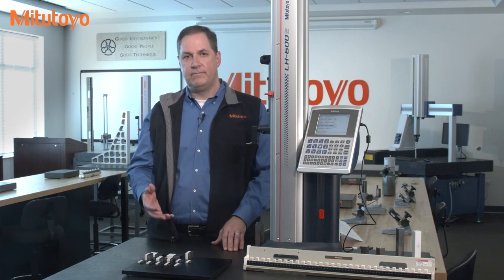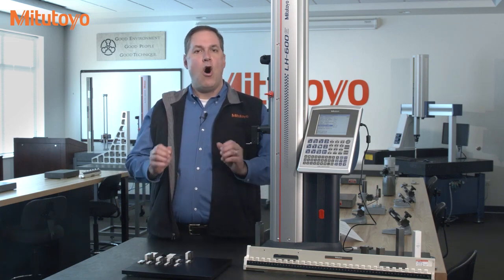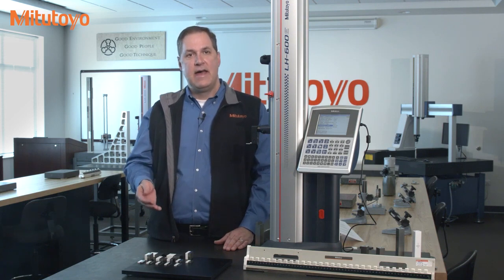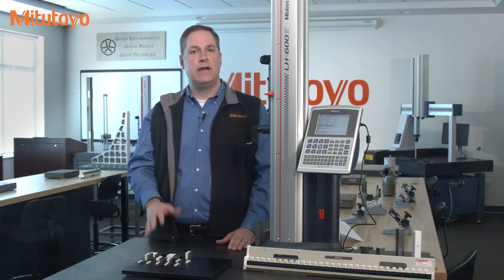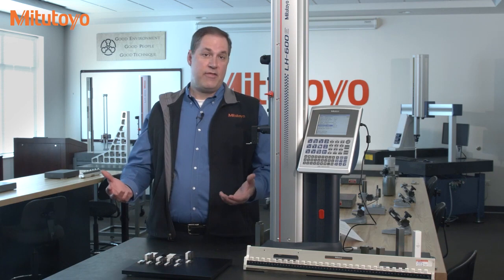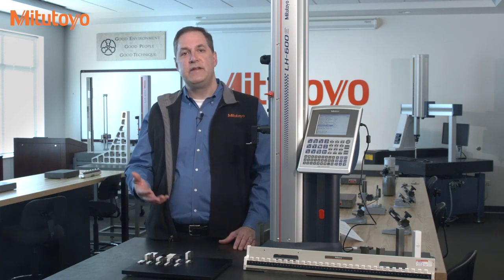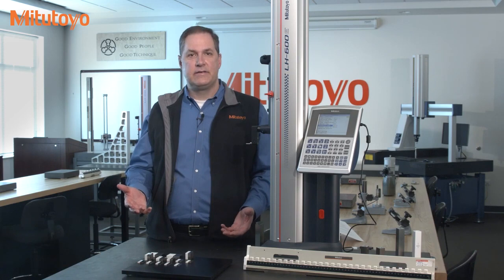So, first of all, dimensions, all sizes, all lengths, all geometric features are defined at exactly 68 degrees Fahrenheit, which is also equal to exactly 20 degrees Celsius. This is the official legal reference temperature found in all national and international standards. So in theory, all your measurements should be done at exactly 20 degrees Celsius. Of course, that's never possible. You never can be that exact, and therefore you always have errors from temperature.